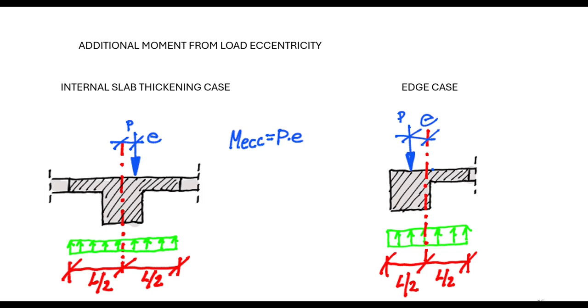And in our software, we are using the second option, and we transfer our additional bending moment to adjacent slabs, or adjacent beams in the corner case. This is also the case described in the approach in the book I mentioned at the beginning.